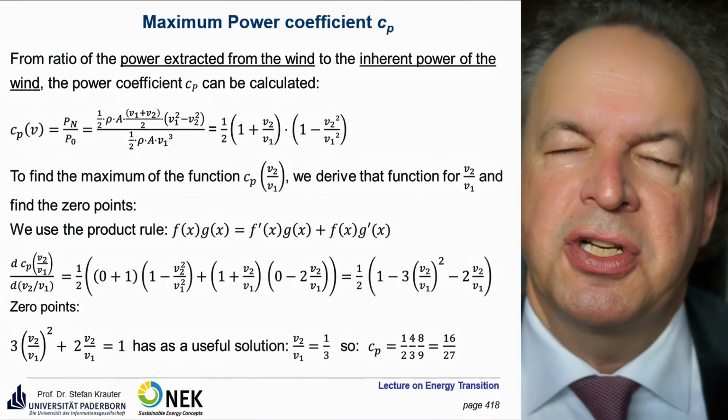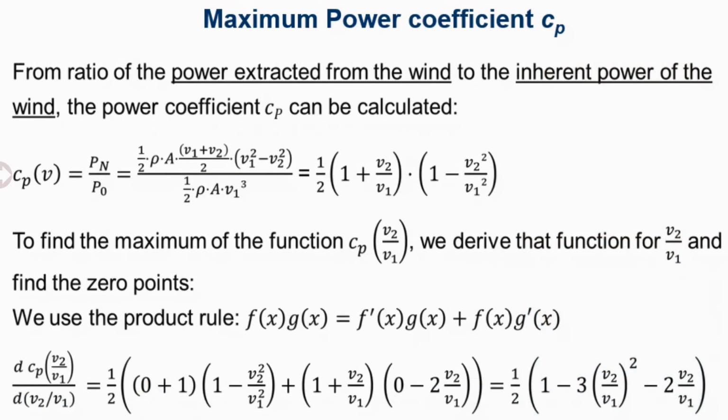So he had the function called the power coefficient. It's the same as the conversion efficiency. So you have here the possible power of the wind, which you see in the lower part of the equation. So this is 1/2 times A times V1 to the power of 3. So this is the theoretical available power, and the actual used power is that one. Remember from the formula before, you can cancel lots of this stuff here, the air density, the area, the factor by a half.